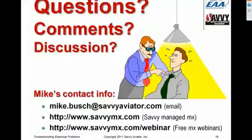I don't know how many of you are old enough to remember the accident where Ricky Nelson died in a DC-3, but they had a combustion heater in that DC-3 that kept popping its breaker, and they kept resetting the breaker over and over again, eventually setting the airplane on fire and killing everybody. So generally, the rule is if a breaker pops, give it a little while to cool off because they are thermal devices. Reset the breaker, and if it pops a second time, don't try to reset it again. Just land the airplane.